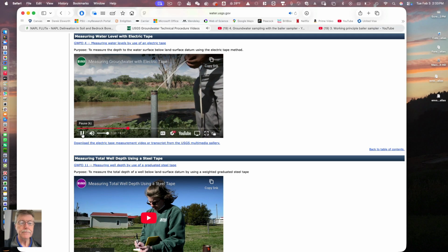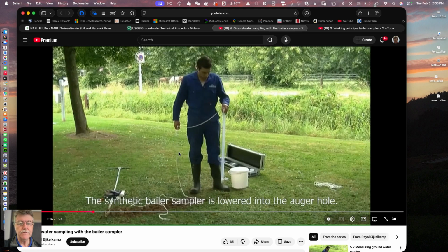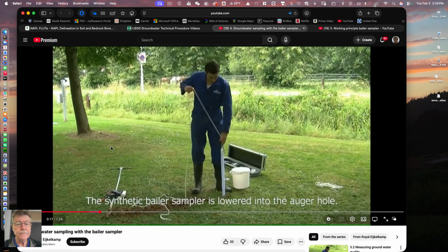At the measuring point, and I guess while we're here, sampling. We haven't talked about sampling, and we don't need to talk about it now. But typically for wells, you'll bail them. You can lift it by dropping a hose or a tube down and applying a nitrogen gas cylinder to blow the sample out of the well or raise it out of the well. But the other, more usual way is to use a bailer,